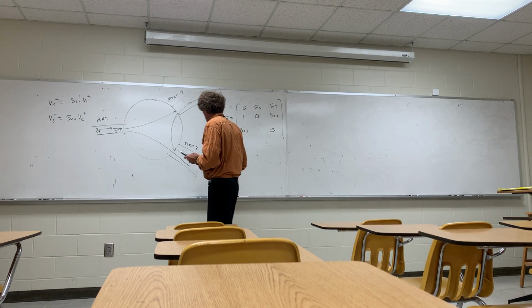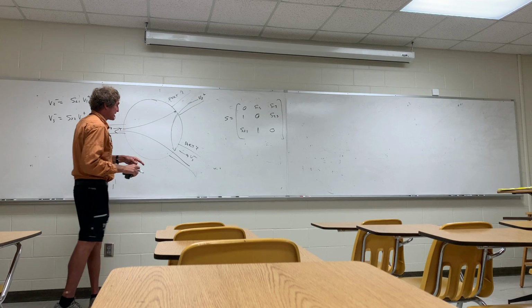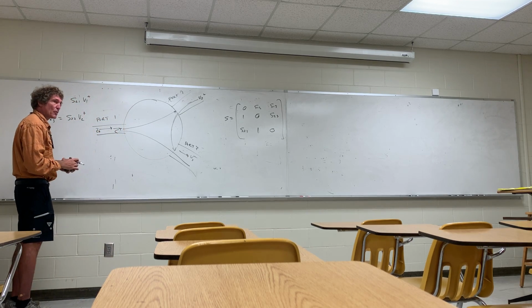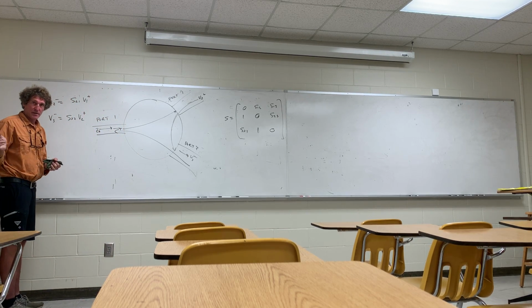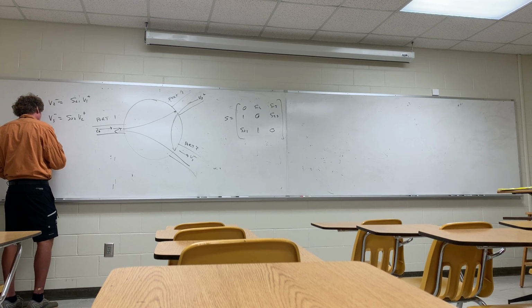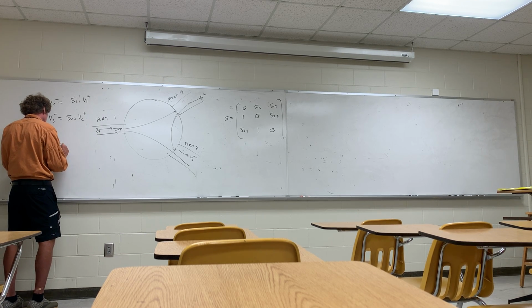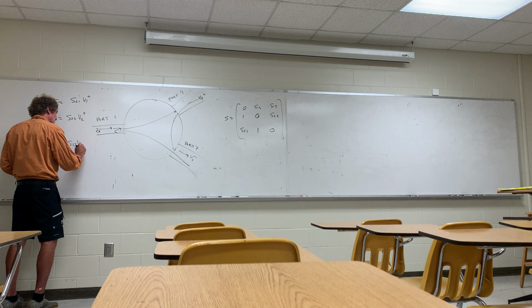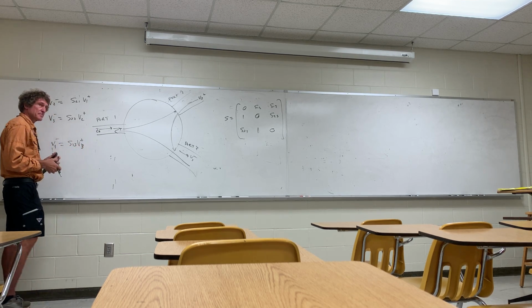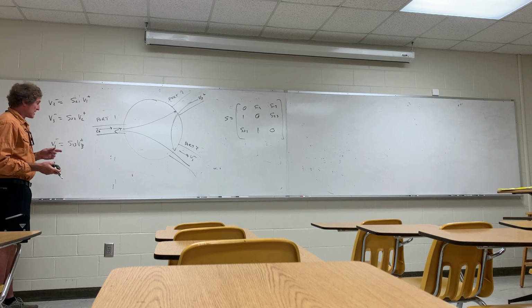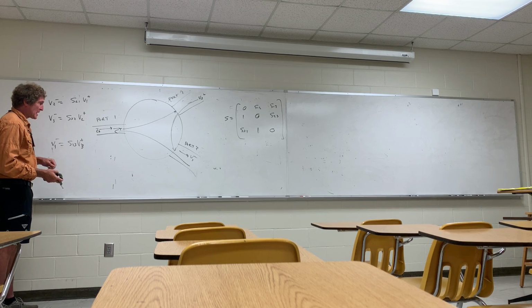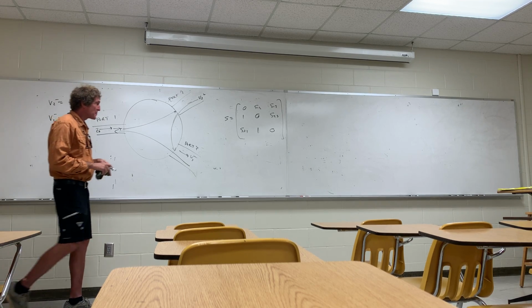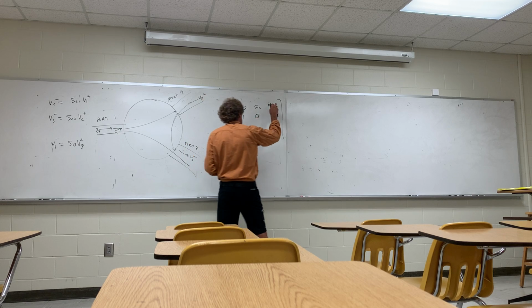Next, finally, everything into port 3 comes out port 1, right? Y'all follow me? So what's that? Well, V1 minus would be equal to S13 V3 plus. Y'all follow me on this? So V3 plus times S13 is V1 minus, so S13 up here is 1.